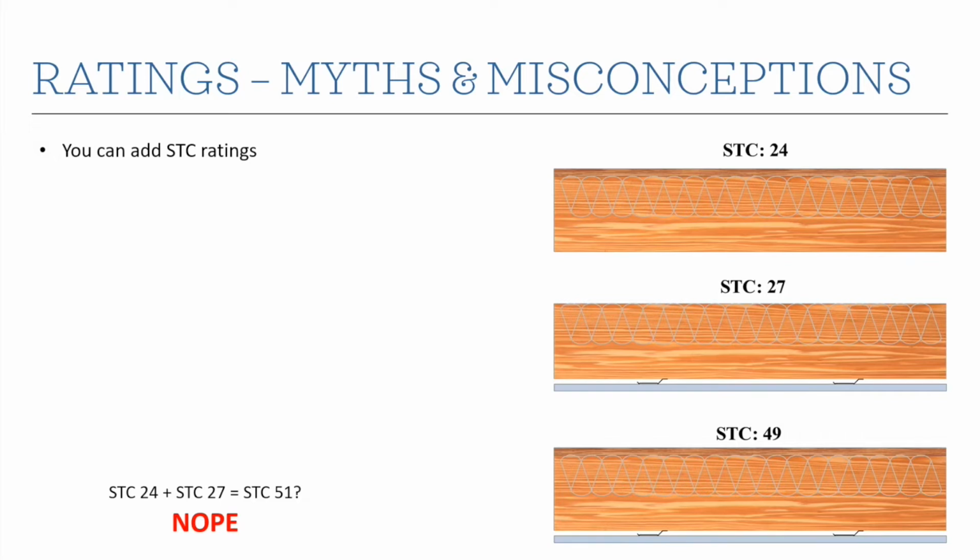That's only a 2-point difference, which I know isn't that big of a deal. But in this case, it made the difference between the added STC rating saying, okay, this thing will meet code, but when you actually go test it, it doesn't. It's below that STC 50 code minimum. So even though it's a small difference, it's a difference that could get you into trouble, right? That creates this liability, creates potential issues.